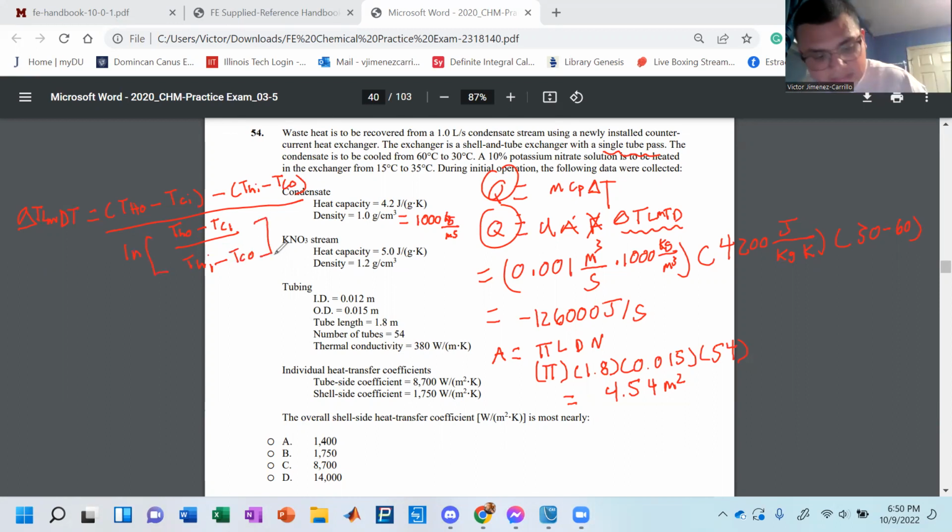Now, it's the beautiful part to this. That is an easy equation to plug and chug, but it's on you to realize that we really, really, really should plug everything in. You don't need to turn anything to Kelvin because it's the difference, so it won't matter. It's temperature in Kelvin, temperature in Celsius, it's the same thing. You can convert to Kelvin, it just wastes time. So, let's write it all out.